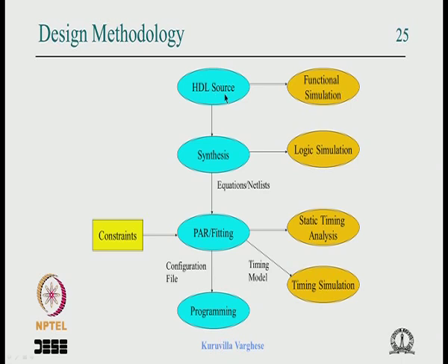When you say Y is assigned A and B, we are not simulating the AND gate, we are just simulating that AND function. Okay. So there is no circuit here, this is the basic source code. It's very fast because if you make syntax errors, you make logical errors, that can be quickly corrected at this point before generating the circuit. So that is that functional simulation.